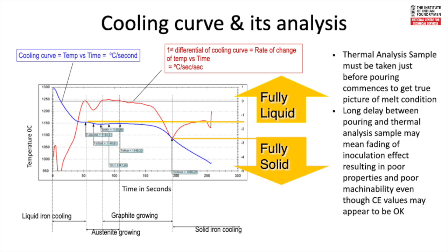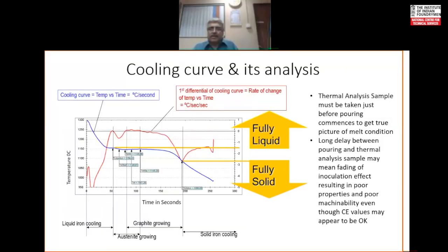Cooling curves, use of thermal analysis, is another technique for assessment of solidification as well as effectiveness of inoculation. I have talked about this in the past also. And a precaution: a long delay between pouring and thermal analysis will give wrong results as a quality control tool because the fading effect will happen.